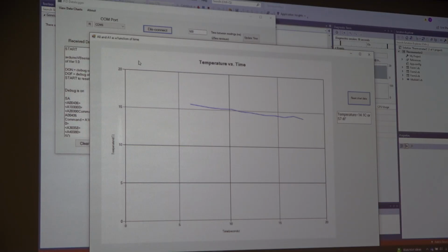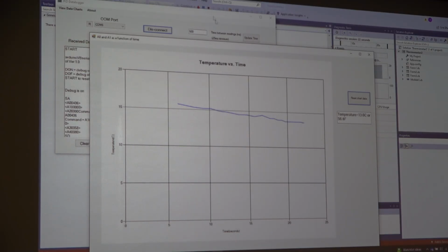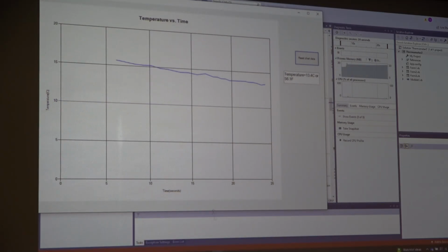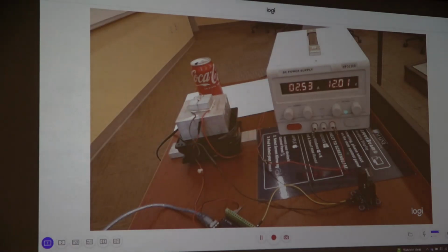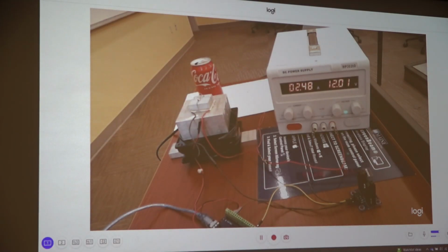So now we've got proportional, we've got integral. What you guys missed, because I was too slow, was the amperage was up at 4.5 amps when it started off. And it's still dying down, okay, because that integral hasn't had enough time to keep accumulating to bring the power back up.